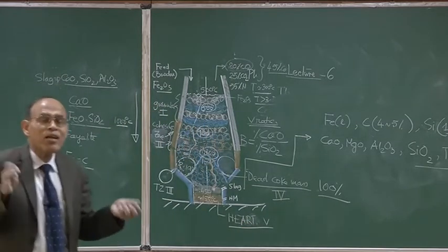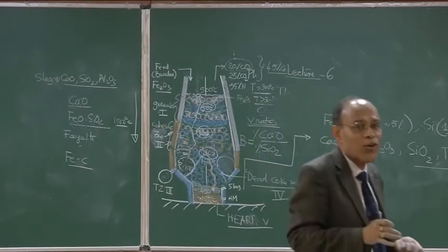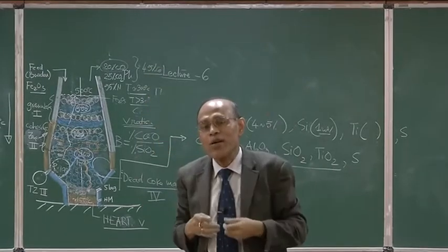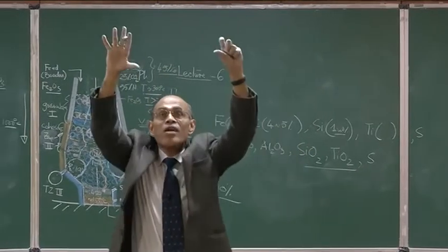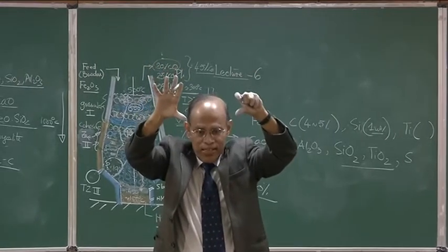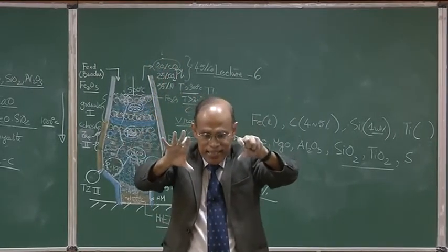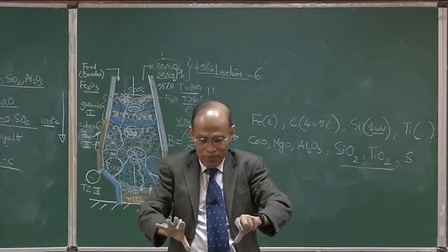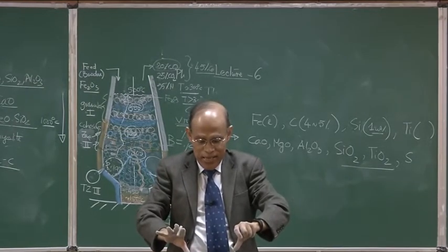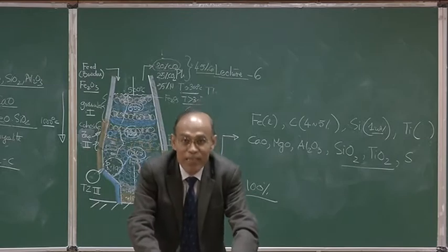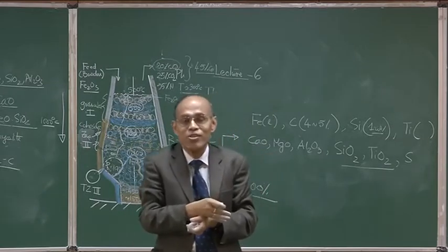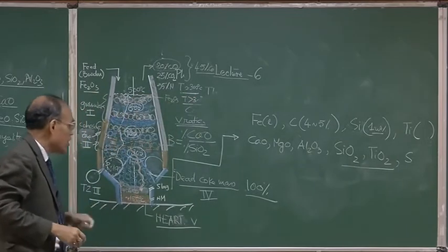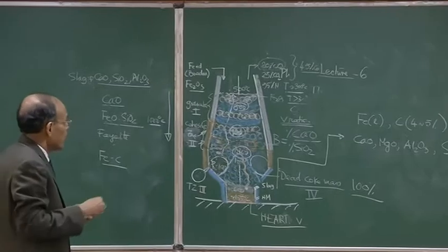So, you can get now a good internal picture if you close your eyes, and then you can visualize how the inside of a blast furnace really looks. In the top part we see the granular particles, and then we see the proportion of granular particles decreasing and decreasing and liquid starting to appear, and then ultimately, if you go down, we have just solid coke particles and liquid flowing all around them, and then at the bottom of the furnace we have two different layers of liquid, the slag and the metal, with a common interfacial contact. That is what one can really see inside the furnace.